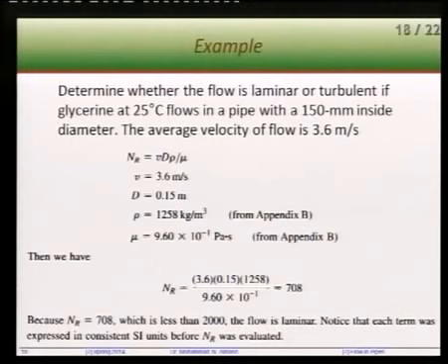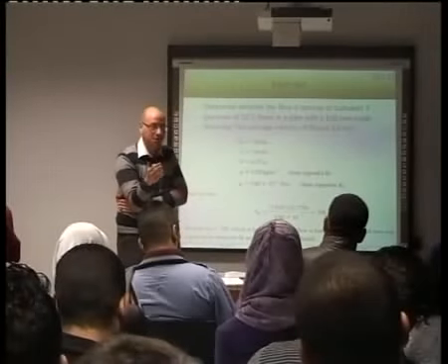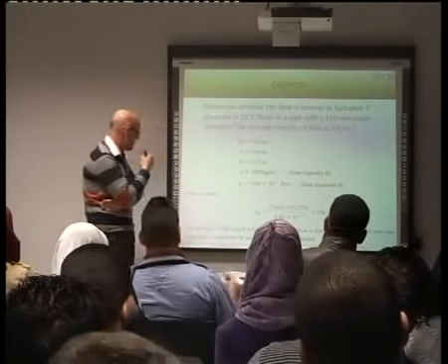There are really some examples here. There's no point really to go through because you already did take that. But at least you might find Reynolds number written in this way. This should not really confuse you. The velocity is given for you, the diameter of the pipe, the density of the fluid, the viscosity is also given for you as well, and you can calculate Reynolds number. Generally, you need Reynolds number to be able to characterize the flow, and then based on that, you can decide what kind of equations you are going to use later on, as we are going to see in the end.